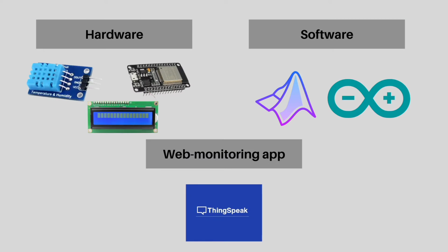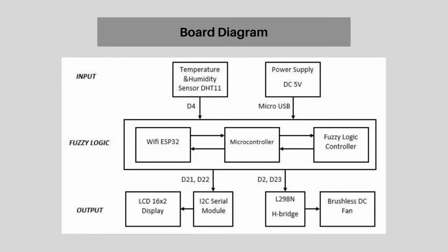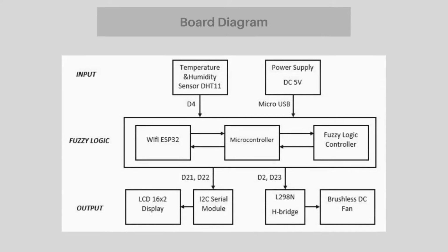For this project, I am using both software and hardware tools to develop this system. As for the hardware, I am using the DHT11 as temperature sensor, NodeMCU ESP32 as its microcontroller with fuzzy logic library, and LCD display to display the information. For the software, I am using Arduino IDE to construct the program and also MATLAB fuzzy logic toolbox for the simulation test. For the web app monitoring part, I am using ThingSpeak, an analytics IoT platform, to display the system information for monitoring purpose. This is the block diagram of the system consisting of input part, fuzzy part, and output part.